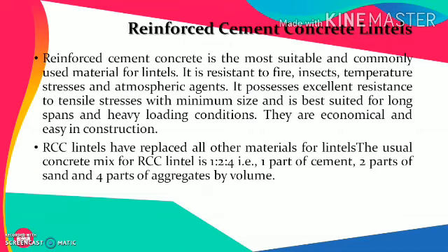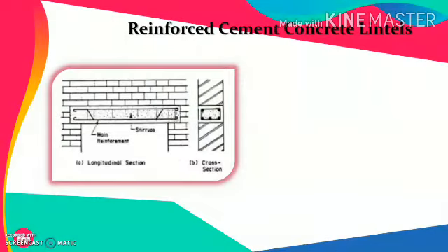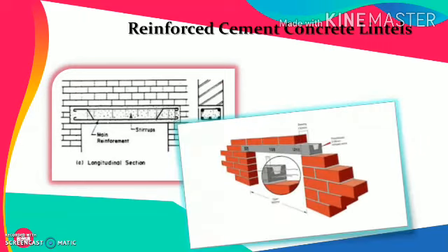RCC lintels have replaced all other material for lintels nowadays. The usual concrete mix for RCC lintel is 1:2:4. Some form of reinforcement is necessary in RCC lintels as plain concrete is weak in tension. This is the schematic representation of the RCC lintels.